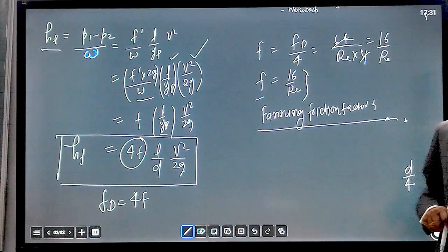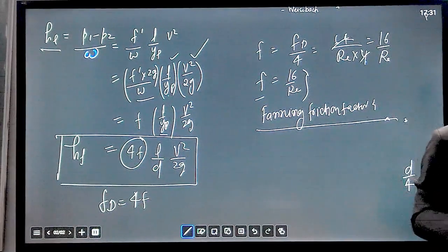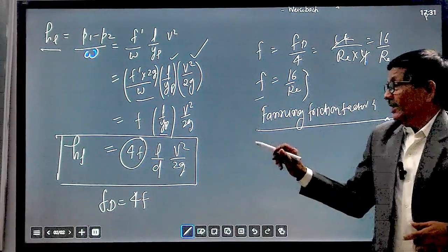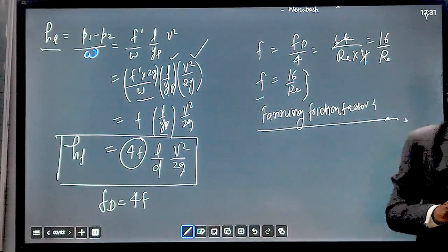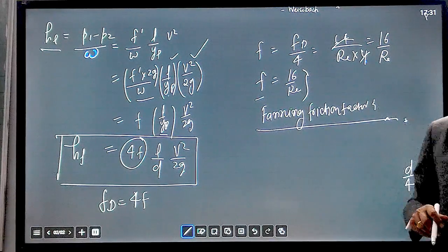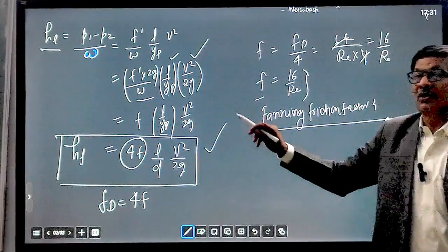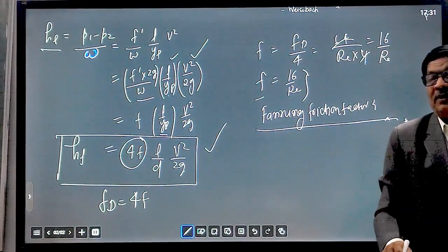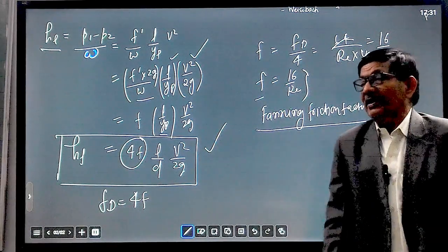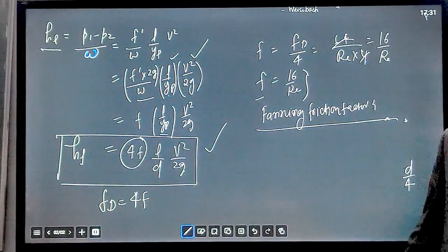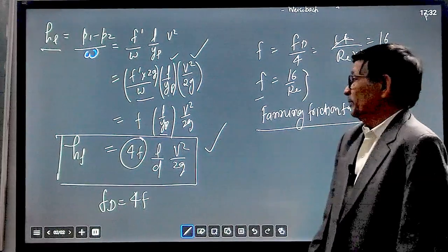So we have to ensure the rate of discharge reaching the refinery for purification and processing work. That has to be maintained by providing pumping power at different locations so that an adequate quantity of fluid can be supplied. For that purpose, we have to find out the head loss: what is the head loss per 100 kilometers, per meter, or per 200 kilometers? On that basis, you have to provide pumping stations. That's why the Darcy-Weisbach equation is a very important relation.